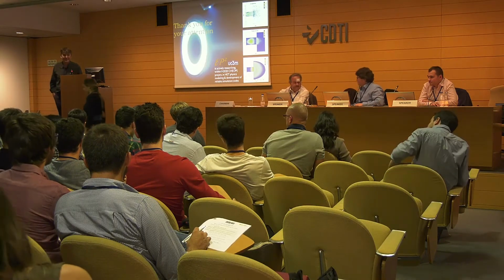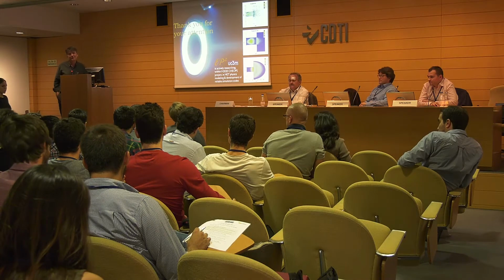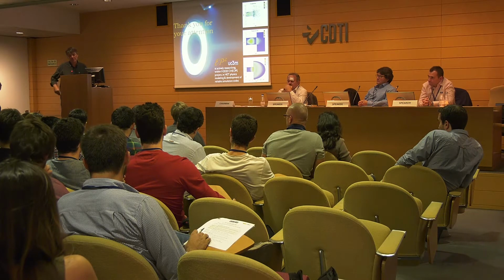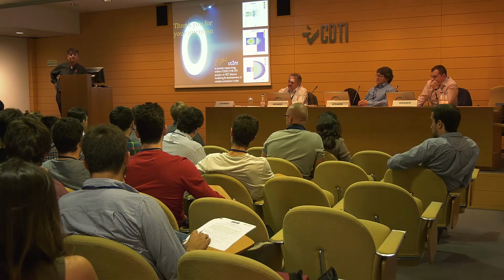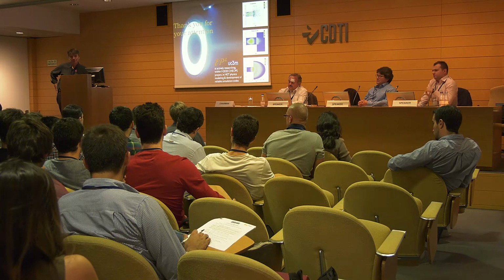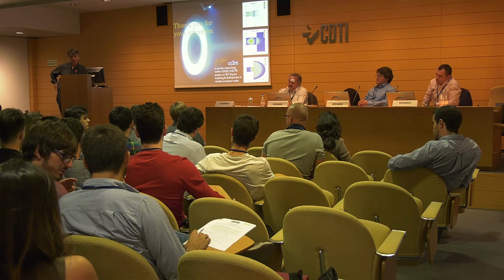Okay, there is another question. Good, questions are coming. I actually have two questions. One is, the topologies of the Hall thrusters you showed are, if I dare say, SPT based with an insulated chamber. Is there any apparent disadvantage of the metallic chamber, the thruster with an anode layer? And the second is, I've read some papers about topologies for small scale, below 100, below 50 watts, the so-called cylindrical Hall thrusters. Are there any activities in ESA in that direction?